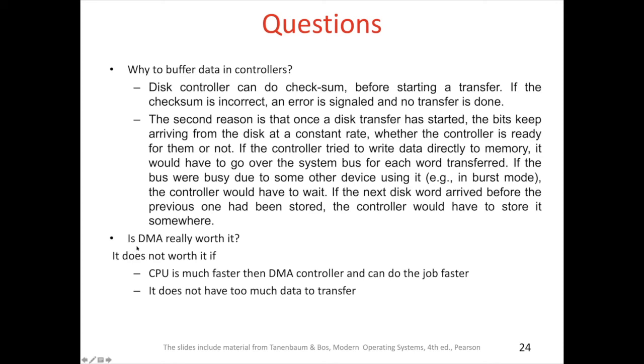Another question is, is DMA really worth it? It is not worth it if the CPU is much faster than the DMA controller and can do the job faster. It is also not worth it if there is not much data to transfer.